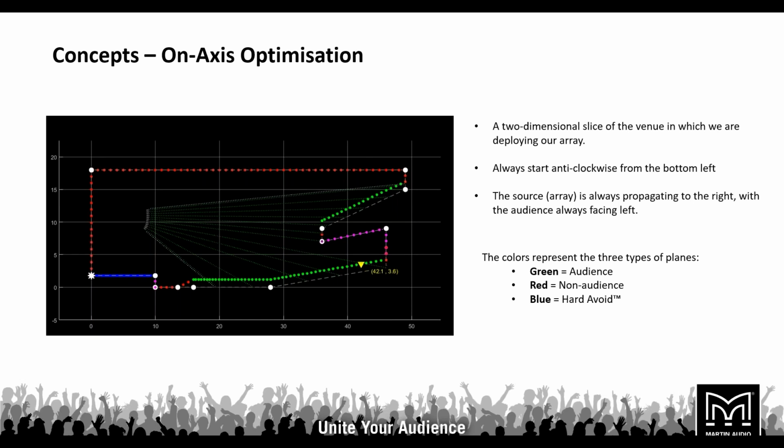So for example, this is very common. You get a vertical slice, a section cut of an installation, say of a church or a performance venue that has a circular balcony. Imagine that's what you're looking at on the screen. You deploy your PA, and from looking at the screen, it looks like the PA is completely dead spot on axis with the center of the venue, but it may not be. It may be facing outwards a little bit because the venue fans out.